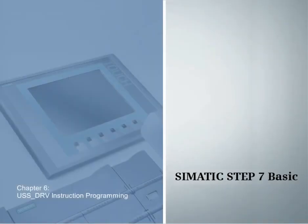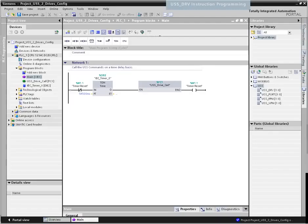Chapter 6. Call and configuration of the USS drive function block. Only call the USS drive FB in the main OB1. We use a TON timer, on-delay, with a delay of 500 milliseconds to guarantee the consistent updating of drive states. In this example, the USS drive call function contains two USS drive calls. Below, we look at how to configure these drive calls.